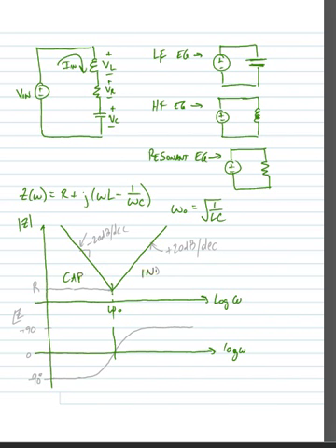Over here, the circuit looks inductive. And we get the associated increases and decreases with impedance. So this would be a minus 20 dB per decade slope, and this would be a plus 20 dB per decade slope. The value of the impedance at the minimum, at the resonant frequency, would simply be whatever our resistance is. And we desire that to be very small if we want our circuit to have very low loss.